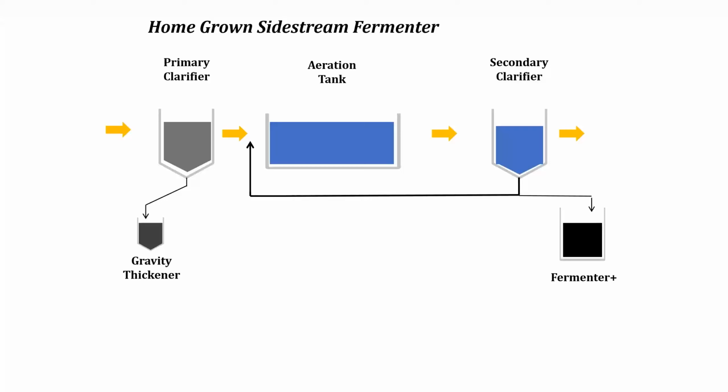It might go through preliminary treatment. If it would settle out in a primary clarifier, that would be a problem. But if you don't have a primary clarifier, you could actually put it in some kind of plant drain that goes back to the head.